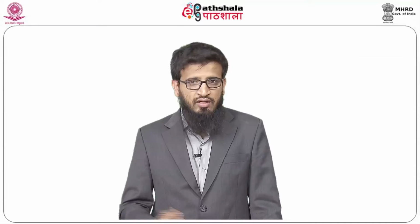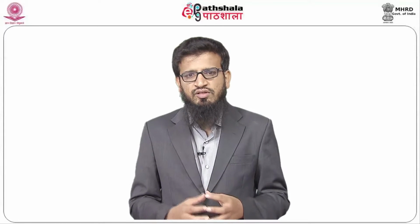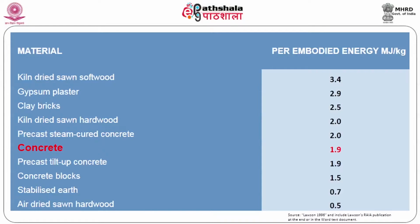a dried sawn hardwood or stabilized mud earth block. Now, most of us, when we are designing eco houses or sustainable houses, prefer stabilized earth block. One of the best reasons why we use it is because of this embodied energy. It uses the least amount of embodied energy compared to most, like the clay brick or the bricks which we use normally, clean dry bricks or whatever bricks we use. Now, clay bricks and clean bricks are 2.5. When you compare 2.5 embodied energy megajoules per kg to 0.7, it becomes quite a difference in terms of the overall energy of the building.